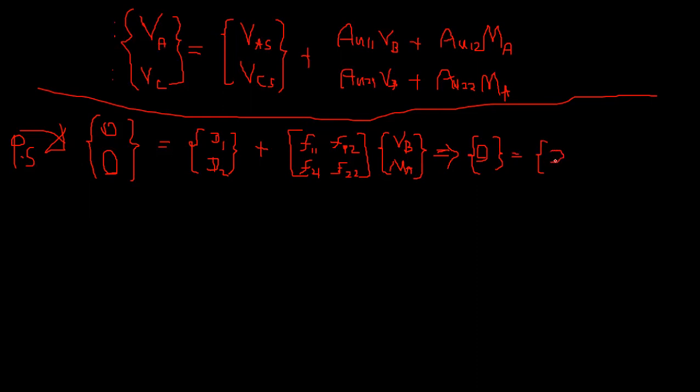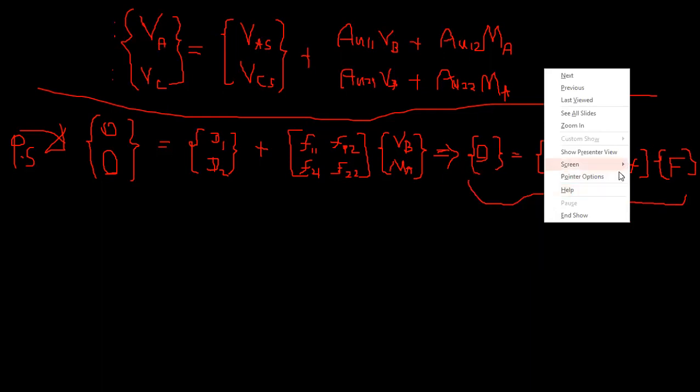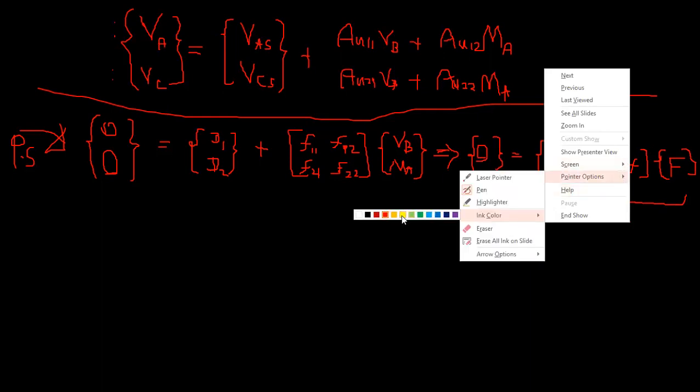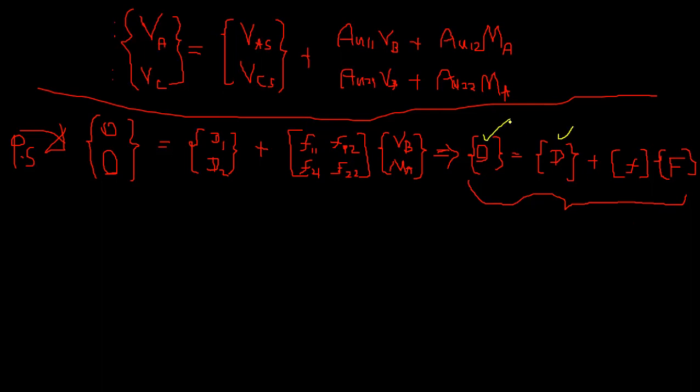This is the D matrix, the displacements, the primary structure. This is, you write the flexibility matrix. So we use square brackets. Why? That flexibility coefficient does not depend on your external loading. This is the force matrix, right? So this is the classical force method equation, right? So yes, you know these things, right? So you can determine this, you can determine this, you can determine this, and you solve for this.